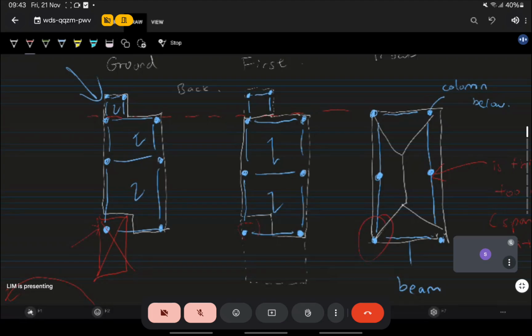So there are issues like this. I let you think how you're gonna solve this. Okay. This is like a puzzle for you. So you follow my principle. You do this for your building first, for your chosen building. Put the columns and the beams and show the slab span direction first, and then we go from there.